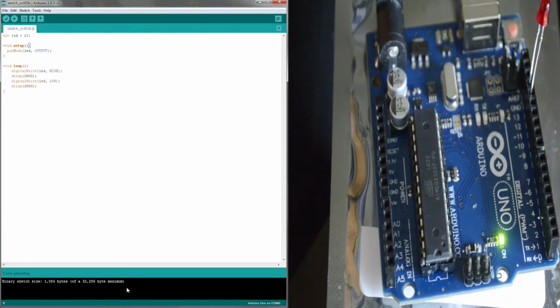This is the first journey on the Unprofessional Tutorials, the Arduino journey, the first episode. So we just made an LED blink for 2 seconds. We can also make it 5 seconds, so I can show you guys that too. Let's put 5,000 in here. We're just doing this for fun now. You guys can play around with this stuff how you like it. Verify the code. The code is running good, and we'll upload it.